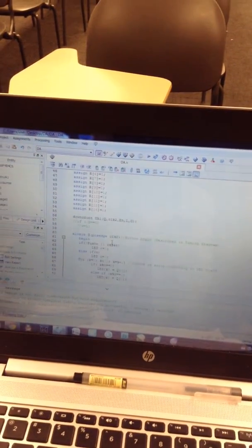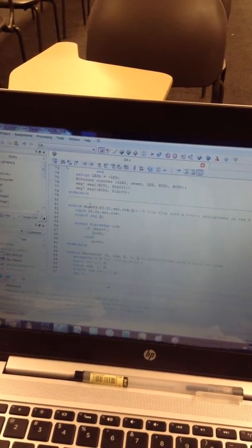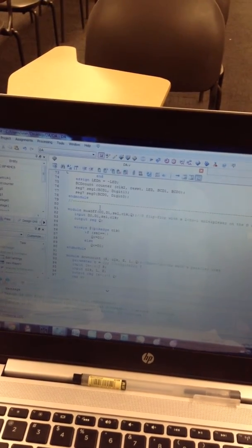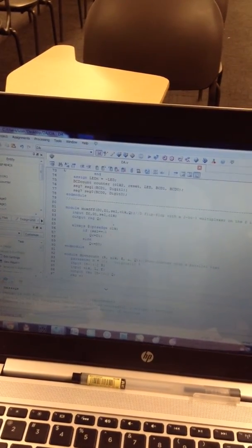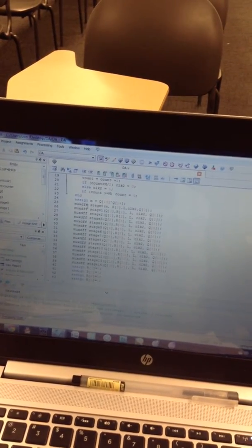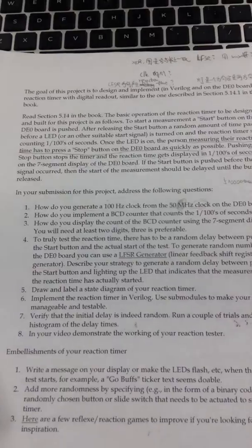So here in my code, I call another new module called MUX DFF, a multiplexer with a D flip-flop. So we will use this with a total of 15 stages, each getting the input and providing the output for the next stage.